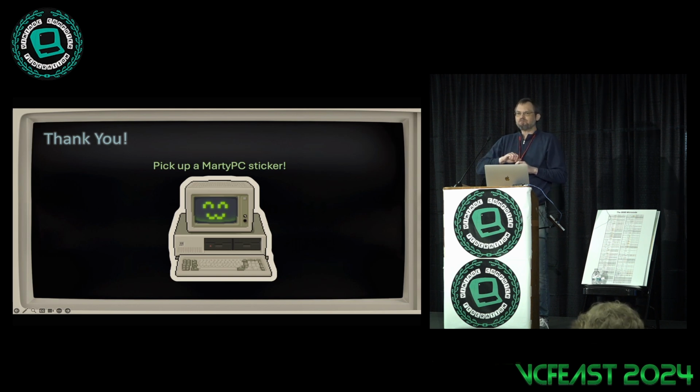I'm a user of the V20 from years and years ago, and this gentleman here asked you, did you ever have a chance to test out the V20 on your board? Yeah, so you could put an 8086 in there or a V20. They're all pin compatible, basically. There's just a few little tweaks. I have to change the code to read the 16 bits off the data bus. And I can actually use the same status line, the BHE line, that the 8087 used to detect an 8086 or an 8088 and just automatically switch my code depending on which one I detect during reset.